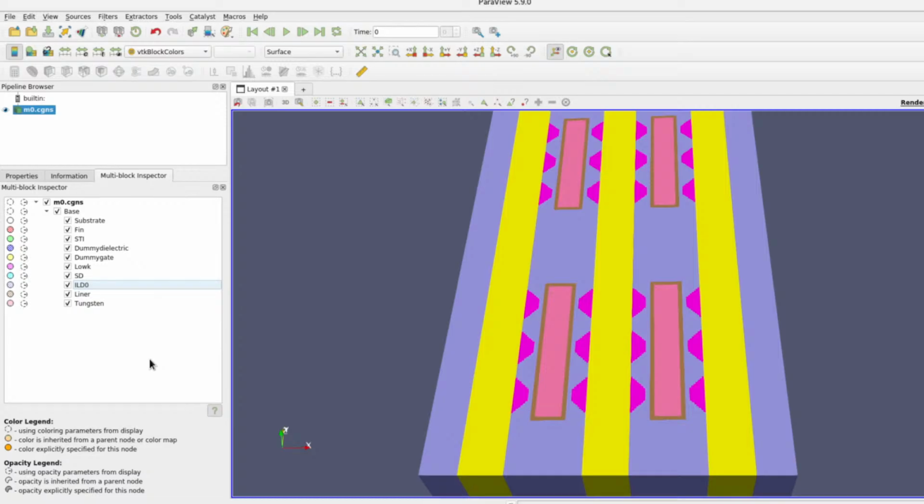Actually, a dummy hard mask is placed on top of a polysilicon dummy gate, but that is not considered. So that introduces some problems in its shape. But anyway, in this initial trial, I just keep this one. So now, as you can see, this part is filled with tungsten, so that will be used for source and drain. Later we will connect it to the other one.